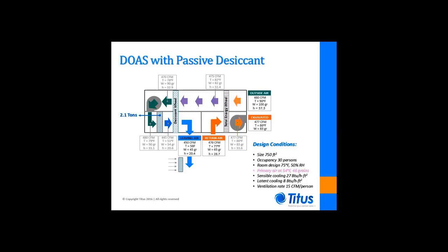It drives the room air induction process through the TAO cooling coil, where additional heat is removed from the recirculated room air. This heat is equivalent to about 0.7 tons taken from the room itself. In total, 2.8 tons of refrigeration has been expended compared to 3.6 tons by the conventional all-air displacement system. That's a savings of 23% on the system cooling energy.